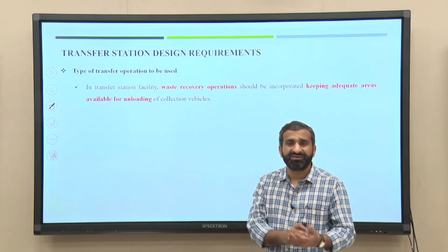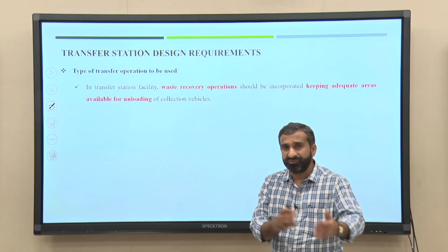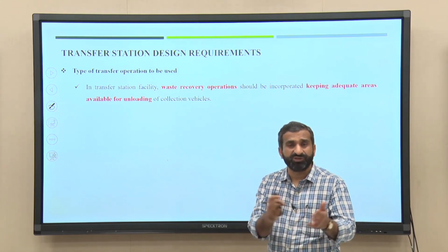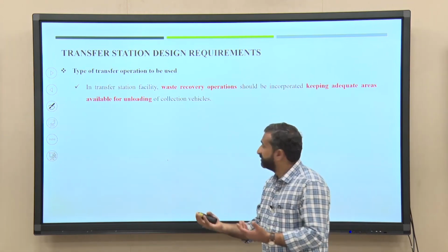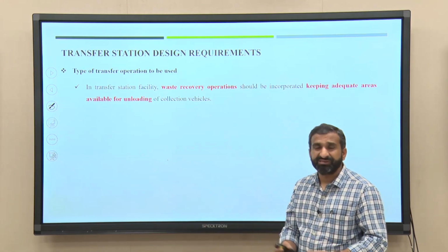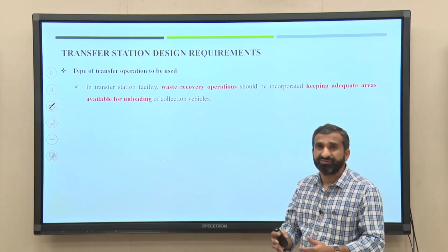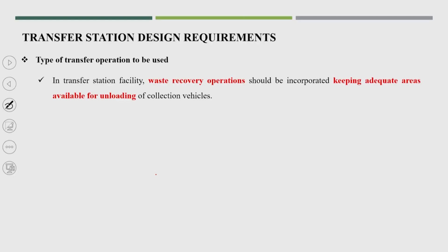It is possible that we are planning the design of a storage load, a direct load, or a mix of both. The transport operation will change, and the area requirement will also change. Based on that, we can design the type of operation required for the transfer station. Especially, the important point here is keeping adequate area available for unloading of collection vehicles.